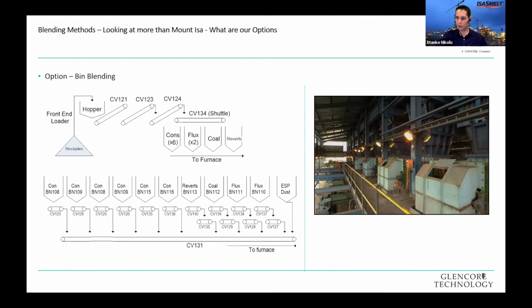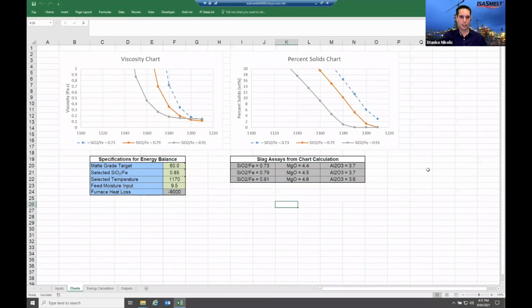Now, I will cross back to the Excel model, and it's finished its calculation. Normally this is doing a mass number of calculations, 30 in all, to be able to do these graphs. It's finished in about 3 minutes or so. That's roughly the amount of time it would take to do all these Gibbs free energy minimizations for these particular conditions. What it has presented to us, and we've split this in 2 views, is a way for us to evaluate the impact on the furnace operation.